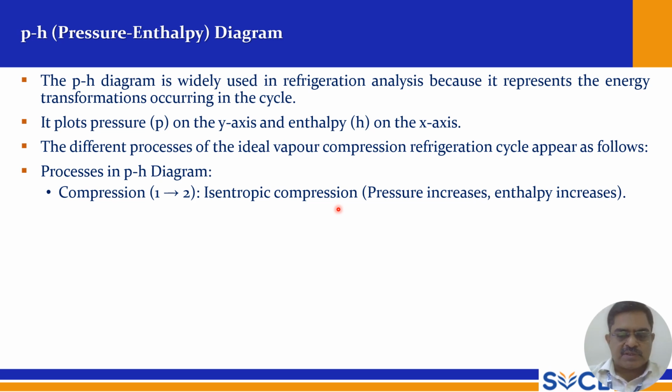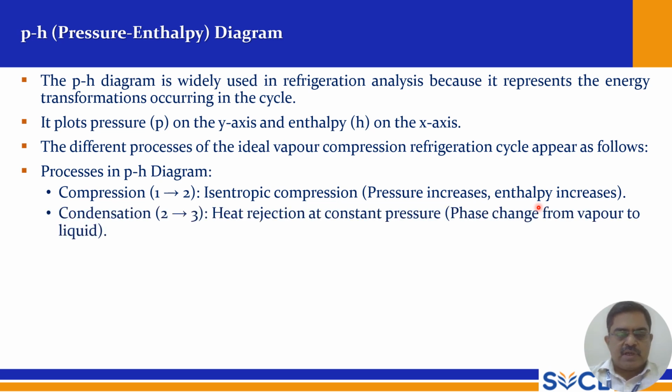That is the actual TS diagram, that is the actual pH diagram, which slightly differs. I will show you that. So here in isentropic compression, during the compression process, what is happening is pressure increases and enthalpy also increases. So enthalpy is also increasing.